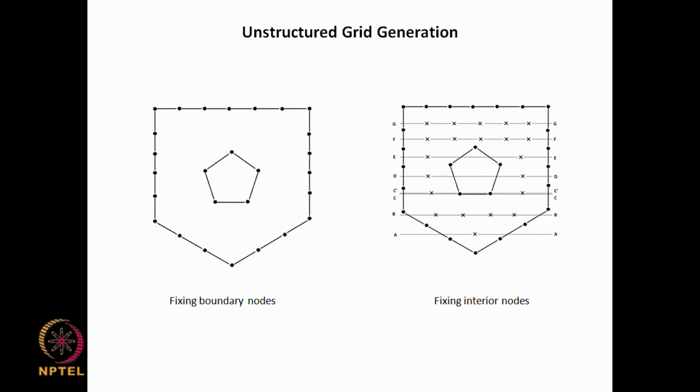So, if you have a grid point inside here, and then if I join it like this to make a triangle, then part of the triangulated domain lies outside the computational domain, and you will be violating the principle that when you put all the triangular tiles together, you should get exactly the area of the computational domain.